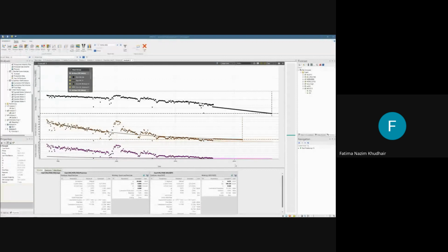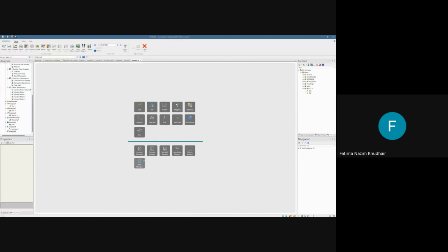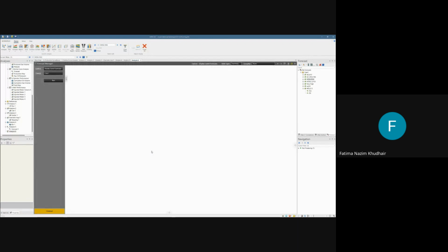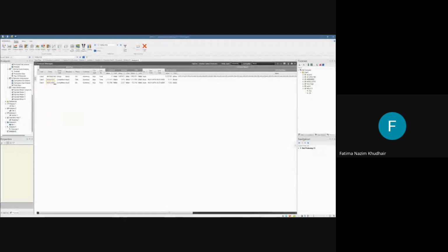Thank you for the question. There is a feature that was added here in OFM 2023 that is called the Forecasts Variance Report. You can find it here in Forecast Manager. Pick your case and then run it. This should show you the variance between your original data and your forecasted data. Also, Taiba, if you have anything to add on this answer, please go ahead.